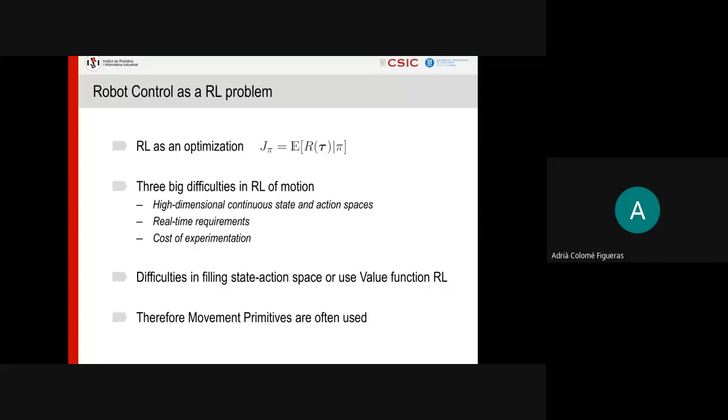learning robot motion. When we talk about characterizing motion for robot learning, we could say, okay, anything can do. Let's just build, for example, a spline representation of motion. Splines are continuous, are differentiable. Everything is easy, but there is a problem with splines, and that is that the parameters on splines have restrictions between each other, so we cannot change one parameter freely, and that is a desired property that we want for learning robot motion.